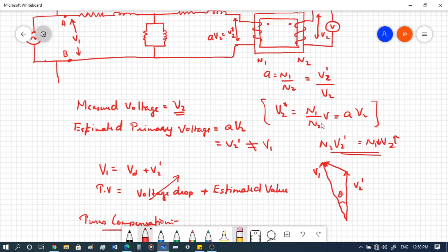This detail won't be given in the potential transformer. It will have a proper nominal turns ratio given, but the actual number of turns will be slightly different in order to compensate this error.